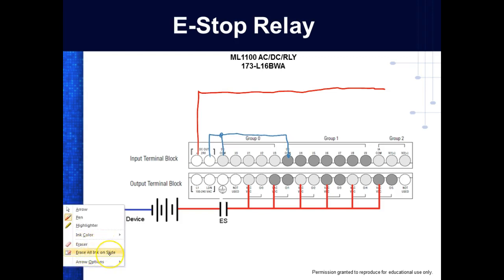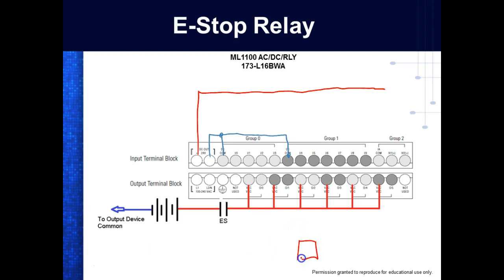Now normally we do what we call a daisy chain. Y'all understand what we mean by daisy chain? So what we might have is a push button. And then the push button would have 2 terminals sticking out the back. And then I'd have another push button with 2 terminals sticking out the back. And I'd have another button with 2 terminals. What I'd do is I'd take this red and jump it to there, and jump it to there, and jump it to there. So that'll be a daisy chain.